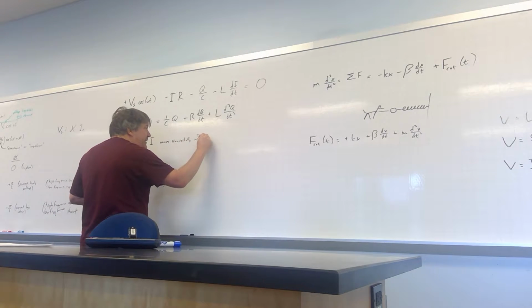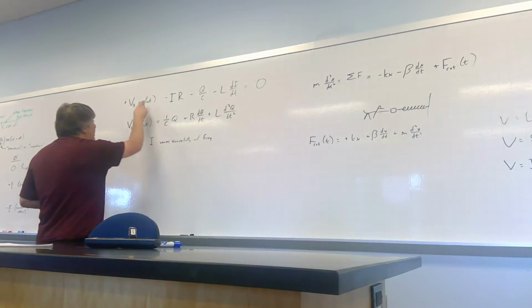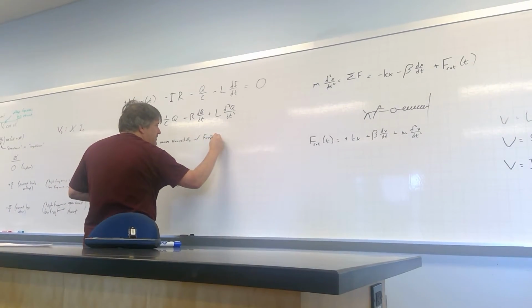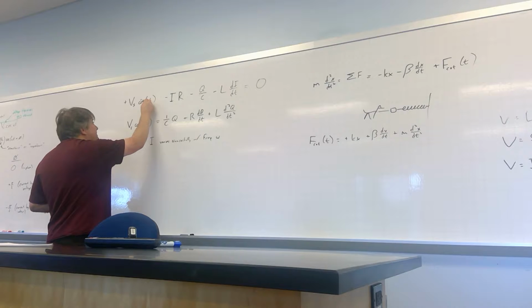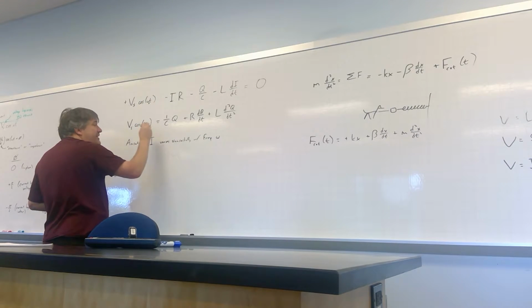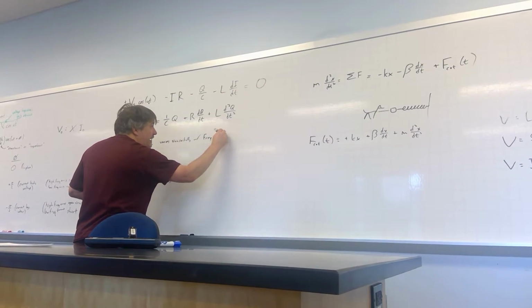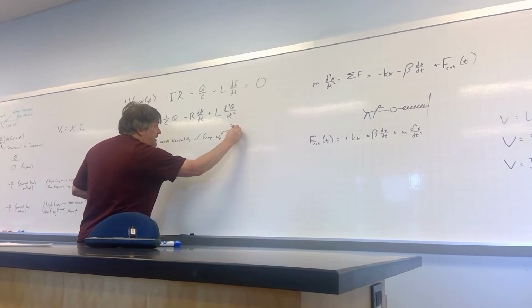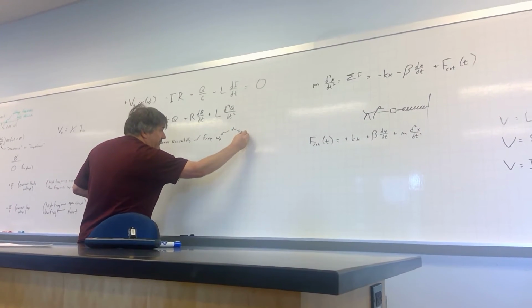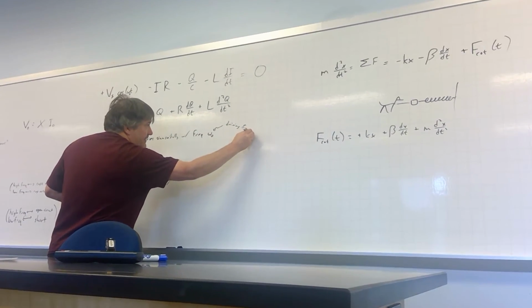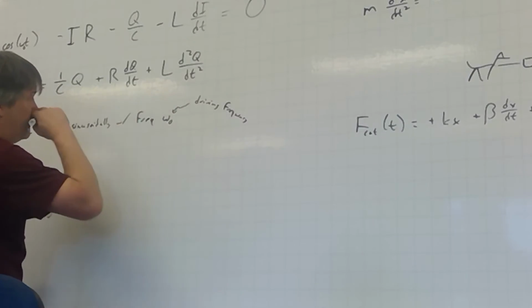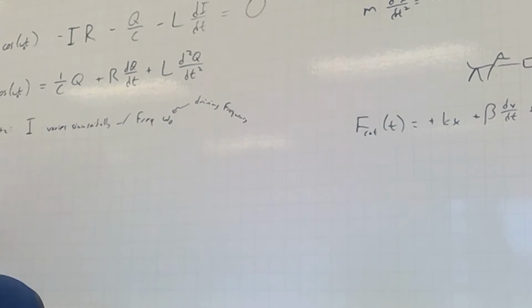And that its frequency is the same as the driving frequency. So omega, I'll even call this omega naught, just to distinguish it from the natural frequency of the circuit, which could be something completely different. I'll say, okay, there's your driving frequency. Are we talking about the current or the charge?